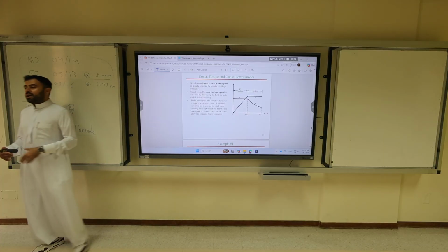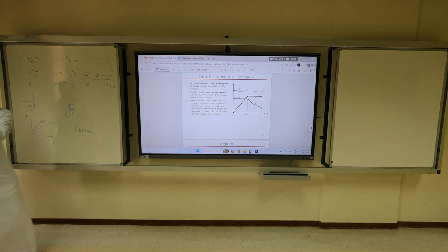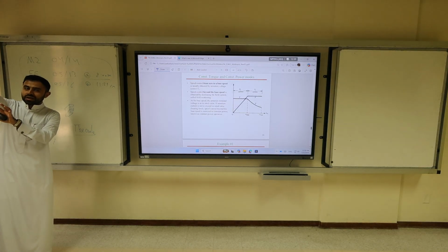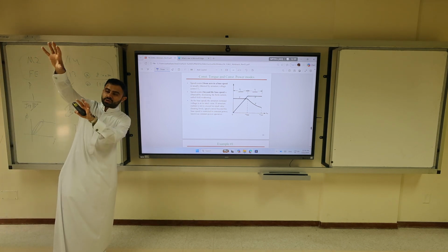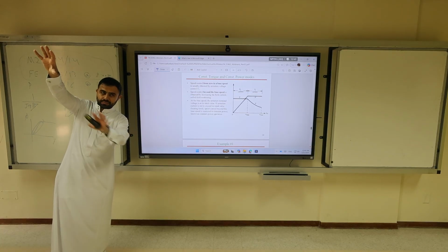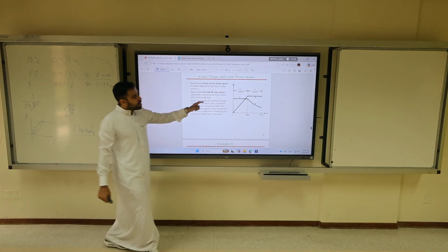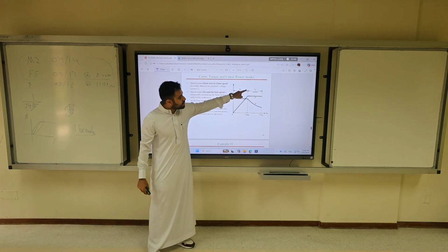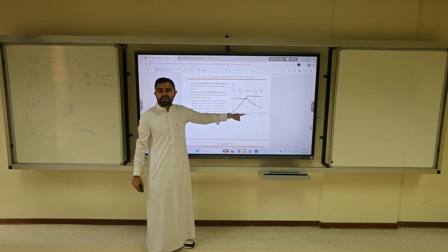What is the optimal way of controlling the machine? Do you remember V over F control? We increase V over F, keep increasing V until we reach V rated. Once we reach V rated, we stop. We only increase the frequency and we go to flux weakening, the field weakening. You remember this in V over F? You cannot exceed V rated. Same story here. What will happen if you go to V rated? You're going to have omega rated, omega base. You cannot exceed voltage. Never ever apply larger voltage in your machine. It's not a smart idea.